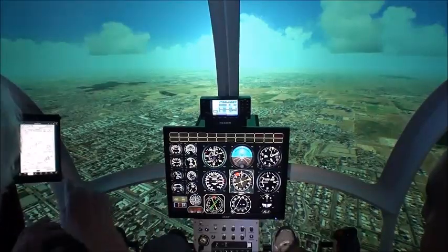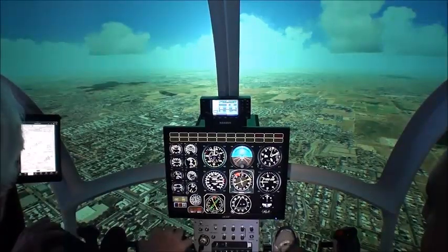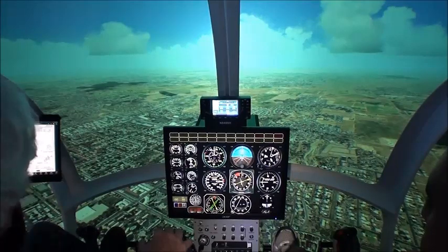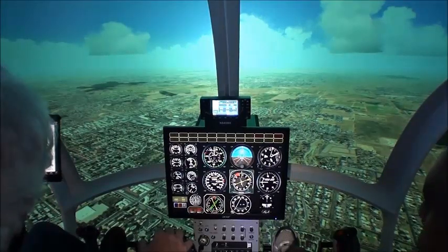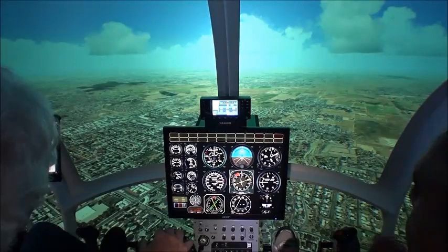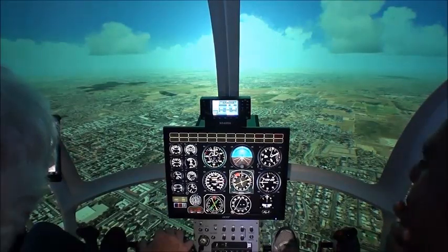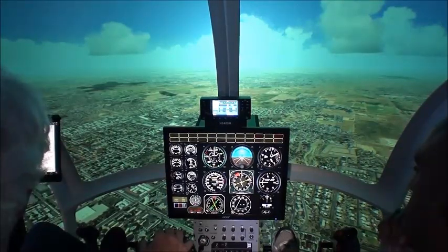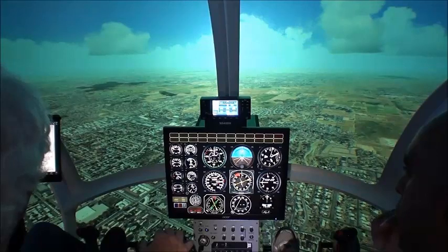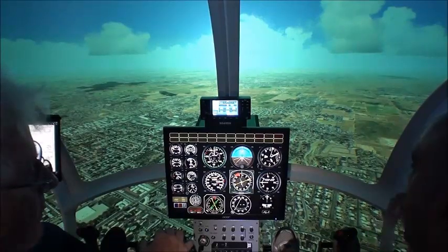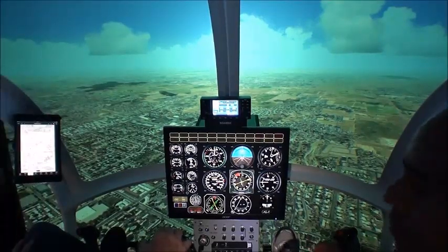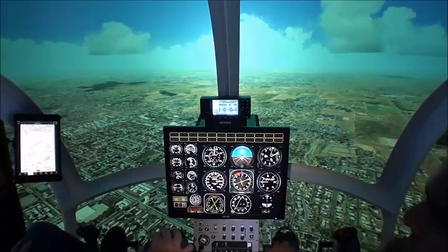We're going to go out, do the procedure turn, and once we fly outbound over the VOR, we can descend to 2,800 feet until we're turned back inbound, and then we're going to go down to 1,780 feet, which is 540 feet above the field. So we're on the wrong side of the field then.